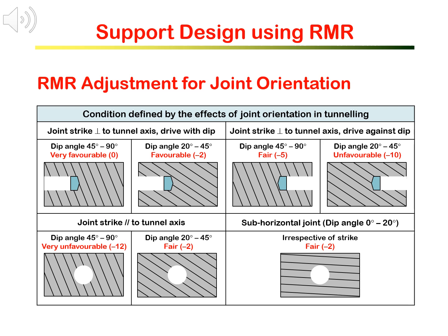In fact, in a later session, when we deal with design of cavern layout and orientation, we specifically highlighted to avoid joints and the line of joint intersection parallel to the tunnel and the cavern alignment. Now, by knowing how the tunnel alignment and advance is geometrically related to the joint orientation, we can make the adjustment to RMR.